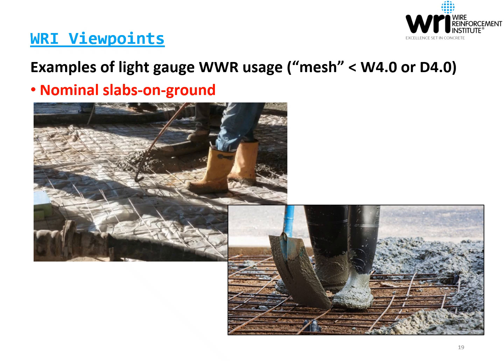The specifier, as we've noted previously, is responsible for defining the design location of the reinforcement as well as the accompanying tolerance that would still allow for the design intent to be achieved. The specifier should also be constructability minded and have an awareness of potential downstream construction challenges that could arise as a function of a chosen design solution, including site activities that could impact material deformability that leads to yielding. On the job site, the contractor is tasked with building the specified arrangement within the tolerance specified.